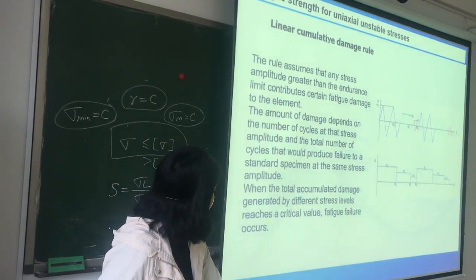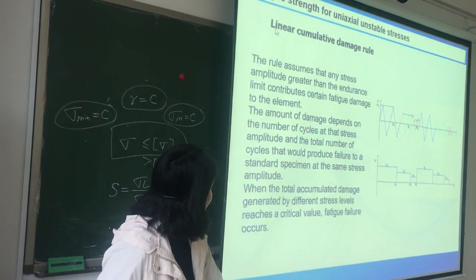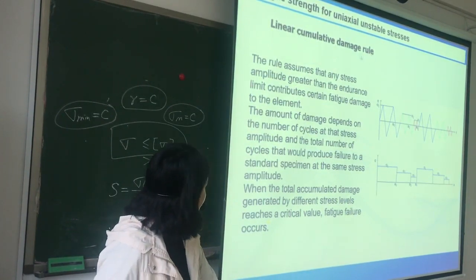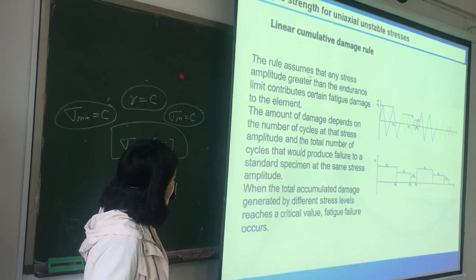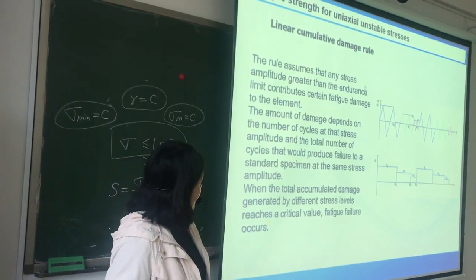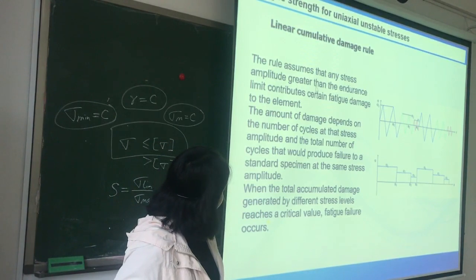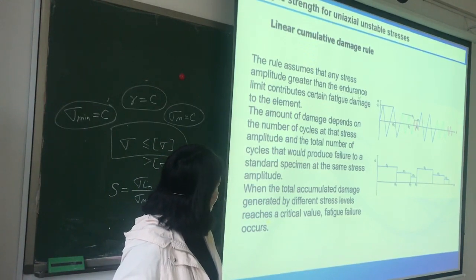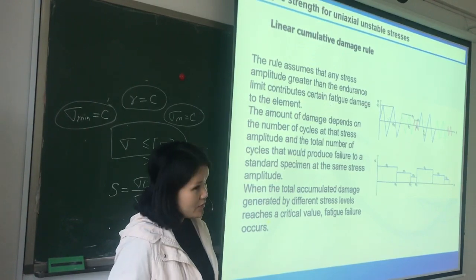And we use the linear cumulative damage rule. In this rule, we assume that any stress amplitude greater than the endurance limit contributes certain physical damage to the element.